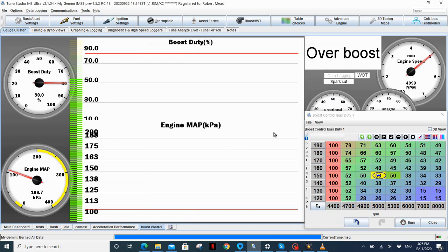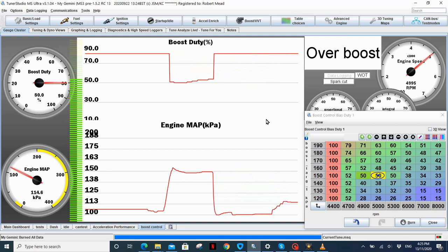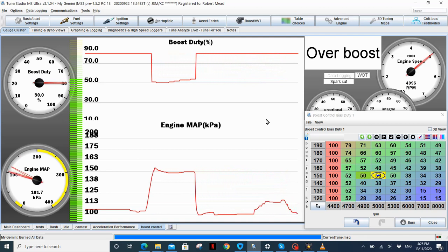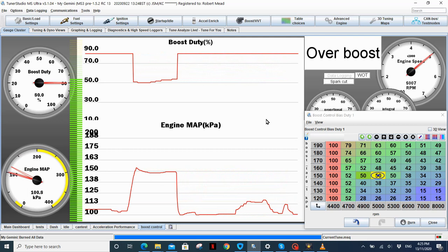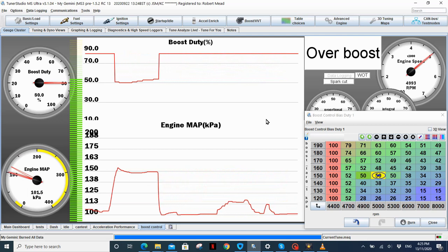Let's have a look now how that affects it, and we'll come on boost and have a look at that there. So the reason why, if you think about it, if you're telling the PID to start doing its work when the delta is 40, that's a massive error signal. So that's going to drive a big change quickly.